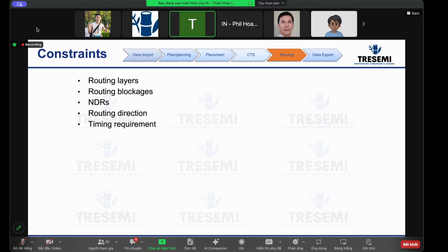You have to pay good attention to those signals, right? And usually we don't want to do it here during routing. We do it way before, right? So those special nets, we're going to route them first, right? And we shield them, eventually isolate them away from the rest of the signals, essentially the random signals, right?